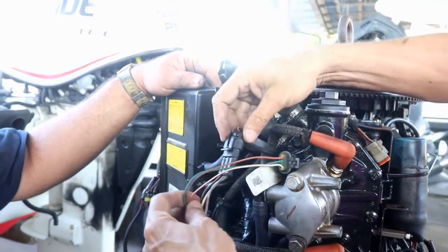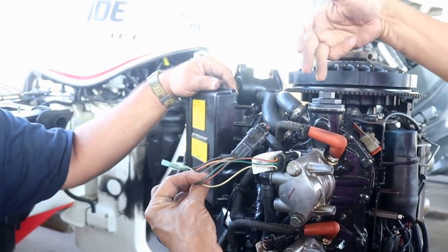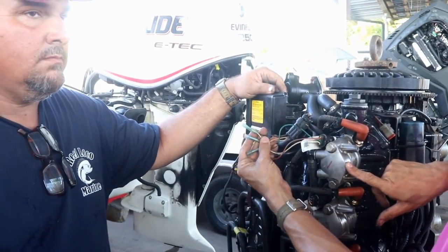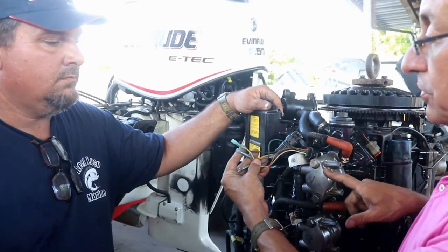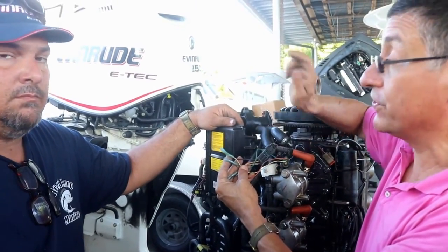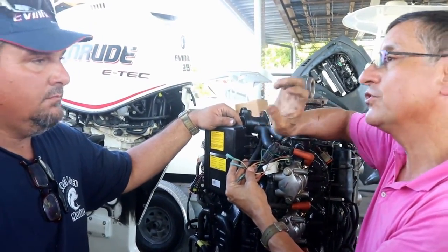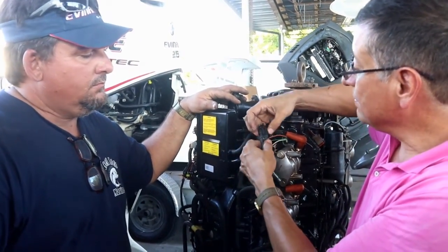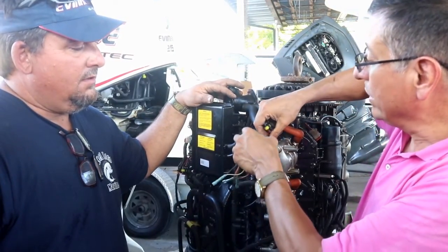That's perfect, because the system is running, the engine is running, and you can verify the voltage. You can verify in this particular engine if the injector is receiving 55 volts from the computer. Correct. 55 volts intermittent, no? Yes, it's controlled by the computer. Exactly the same, you can do it with the rest of the sensors.